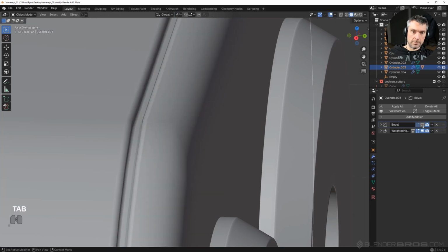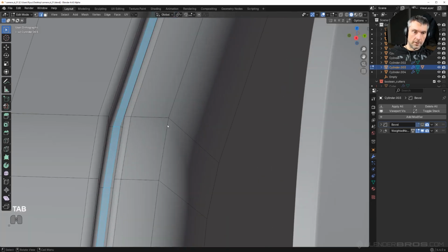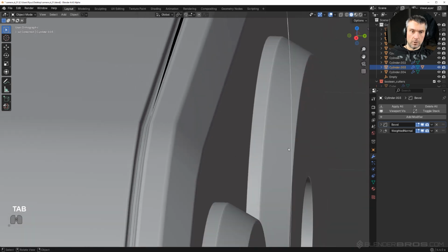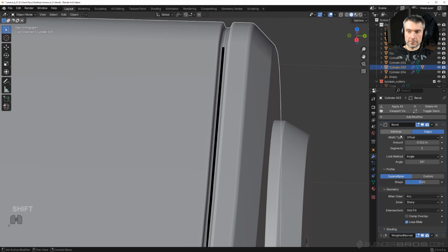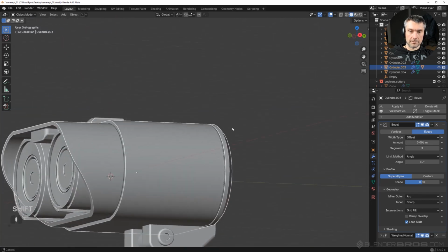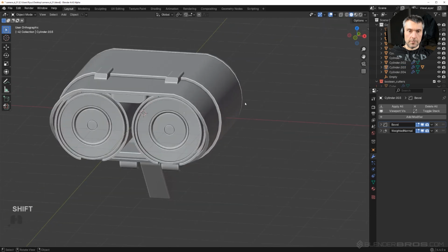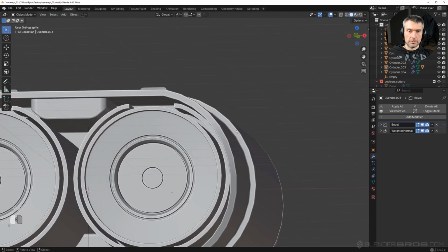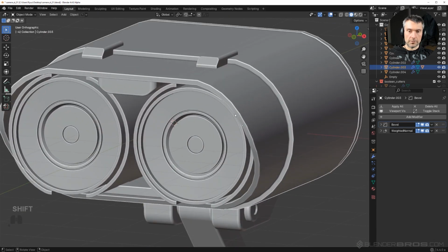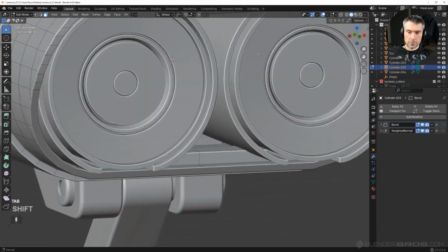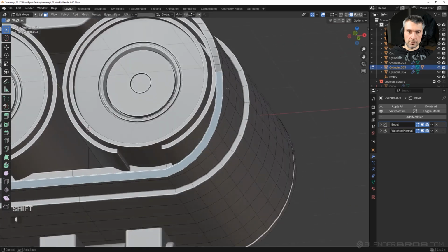So if I turn off the bevel, you'll see what I mean, right? Now the bevel is a little bit too large because it's overshooting, you see that? So we need to lower the size of the bevel, just a little bit, boom, you see? You got nasty shading over there. And that would do. I mean, we could also add subdivision here to this section, but this would require a bit more work, because we would need to fix the topology here on this face.